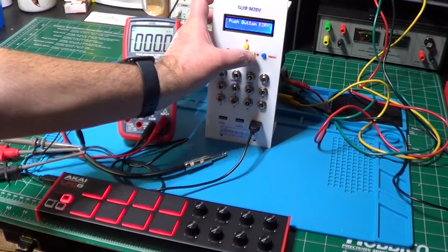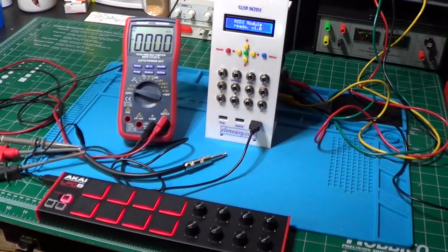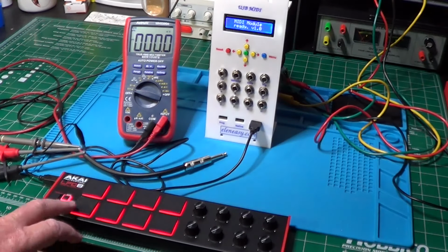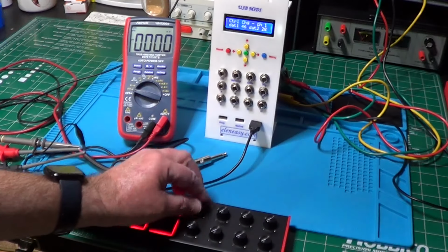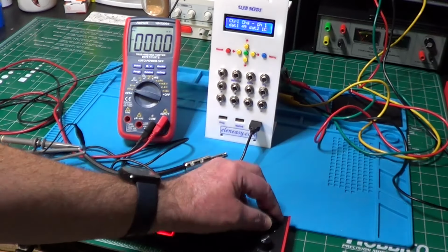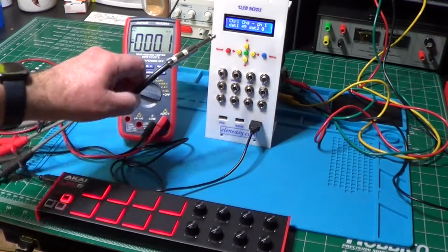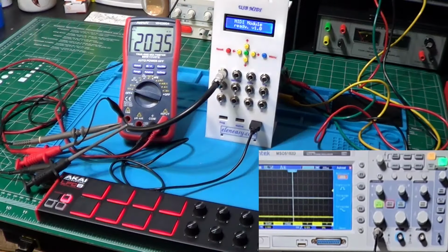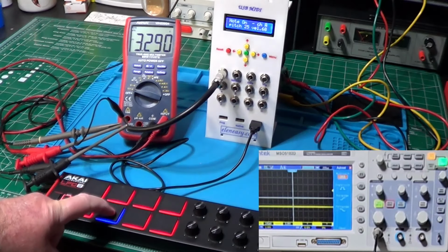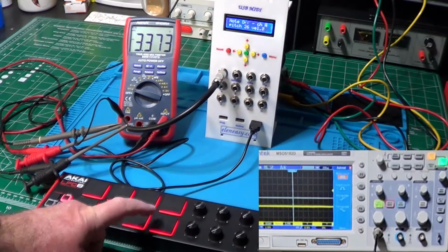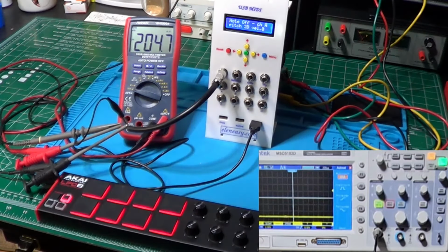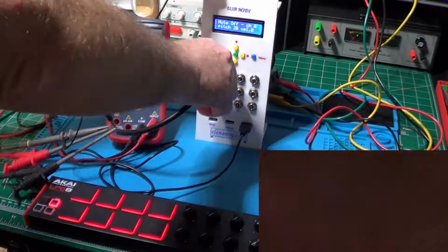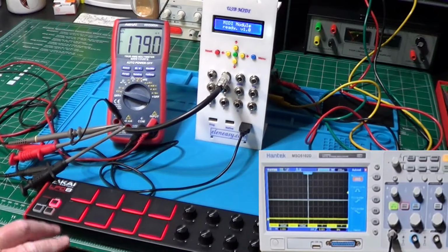First I tested all the push buttons except for the menu button, for which we don't have any software yet. Then I checked that the MIDI module would recognize all the MIDI messages emitted by the LPD8. And finally, I used the digital voltmeter and the oscilloscope to verify the value and shape of all the emitted signals. Once I was satisfied with all the test results, I installed the MIDI module on the synth rack.